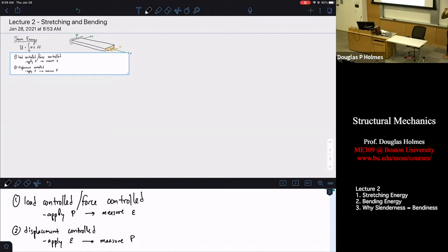and it just goes from a soda can to being crushed immediately. The behaviors there are dramatically different depending on if you're imposing a load and saying it can displace however much it wants, in which case it can dramatically change, or imposing a displacement and just measuring how much load is required to impose that displacement. But you're saying you can't displace more than the amount I'm letting you. Seems really similar. The behaviors can be quite different.